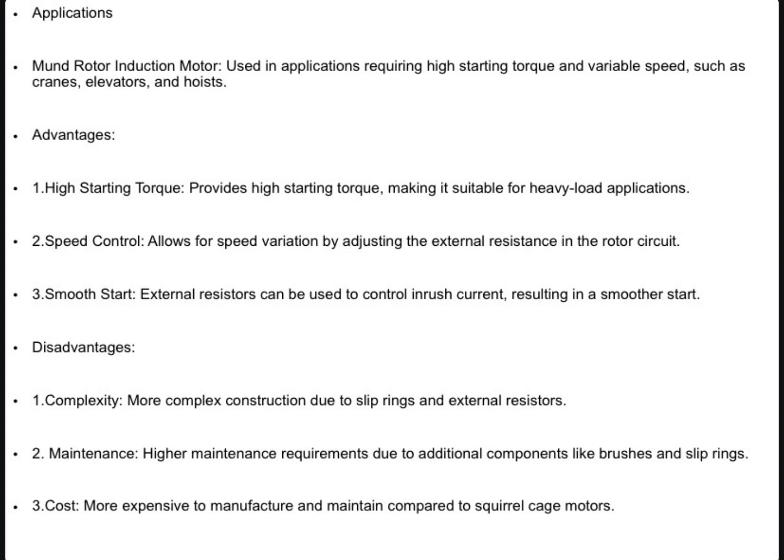Advantages. 1. High starting torque. Provides high starting torque, making it suitable for heavy load applications. 2. Speed control. Allows for speed variation by adjusting the external resistance in the rotor circuit. 3. Smooth start. External resistors can be used to control inrush current, resulting in a smoother start.